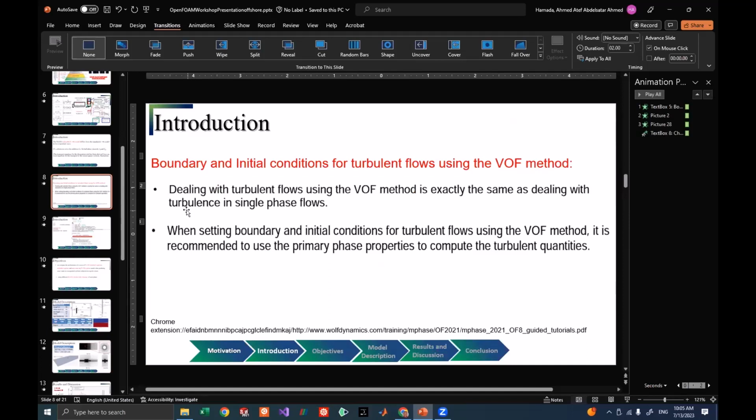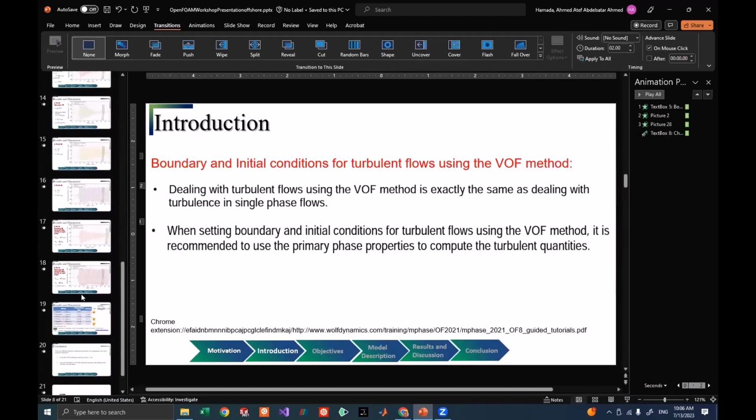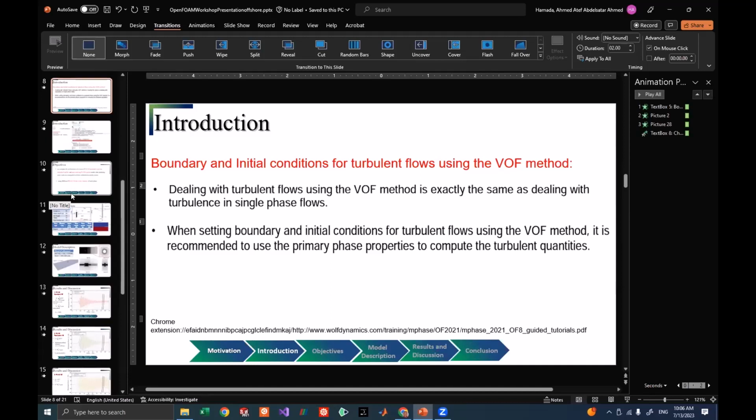I have tried PANS for a similar case in OpenFOAM, and my first question is that you start with FK as 0.7 and 0.2, but when you look at the end of the simulation in ParaView or Tecplot or the post-processing software, do you see that the same FK is maintained throughout the simulation, or does it keep changing in some regions or in some time steps? I use the same FK 0.2 for the whole domain. It's not using hybrid for different meshes like the hybrid LES and RANS. It's just FK fixed for the whole domain.